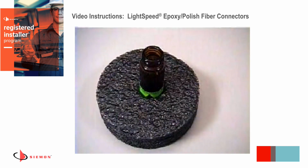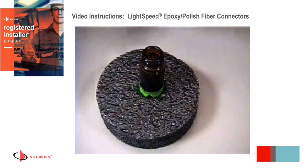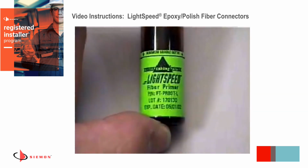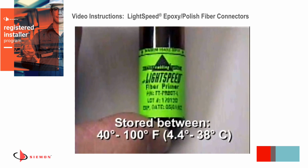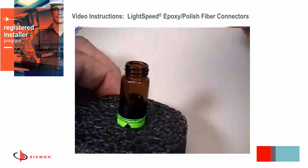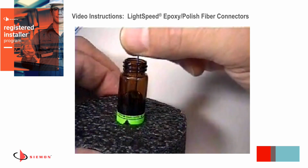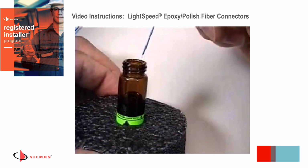Always inspect the date shown on the label of both the adhesive and primer to be sure the product has not expired. When not in use, both the primer and adhesive should be capped and stored within the temperature range indicated. Dip the entire exposed length of fiber, including some portion of the buffer material, into the Lightspeed primer and place in a protected area.